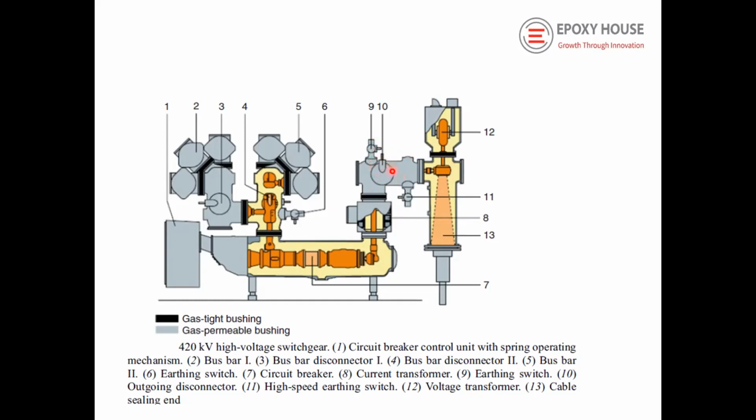The position of the disconnector can be viewed, and each individual gas compartment can have a separate rupture disc, because whenever any fault happens, or it is short circuited, a big explosion would be possible. So rupture discs are given. When the pressure increases more than the design value with a certain margin, the rupture disc operates, and it releases the high pressurized gases out.